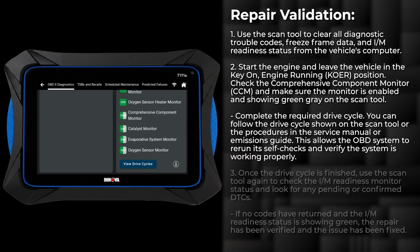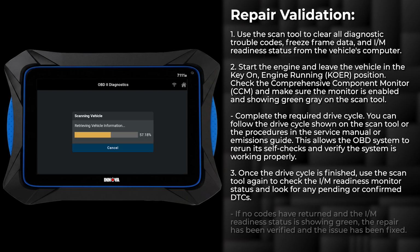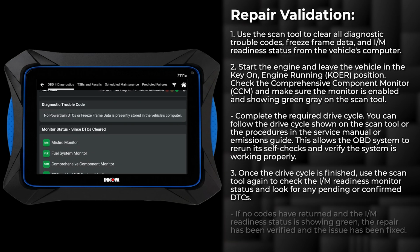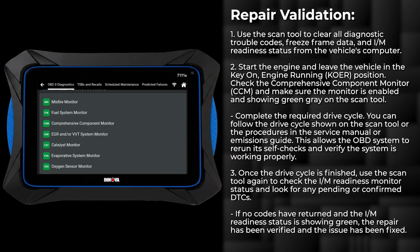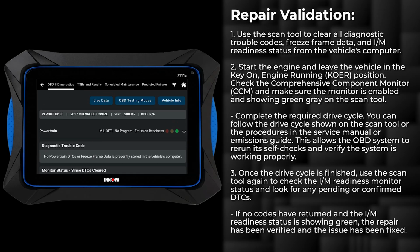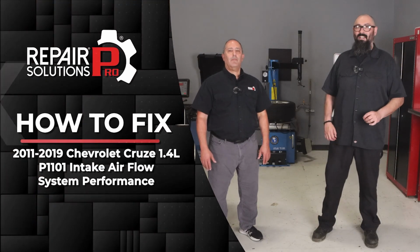You can follow the drive cycle steps shown on the scan tool or use the procedure listed in the service manual or emissions guide. This allows the OBD system to rerun its self-checks and verify the system is working properly. Once the drive cycle is finished, use the scan tool to check the I&M readiness monitor status and look for any pending or confirmed trouble codes. If no codes return and the readiness monitor shows complete, which is green, the repair has been verified and the issue is fixed. This concludes the entire process for fixing P1101.